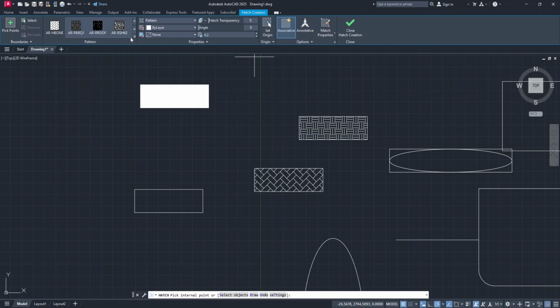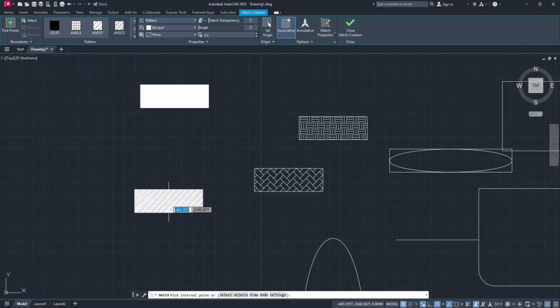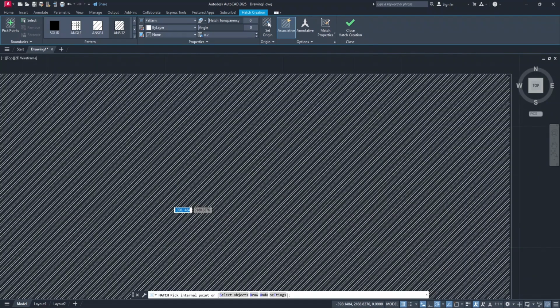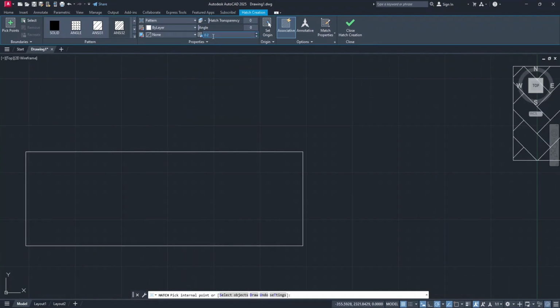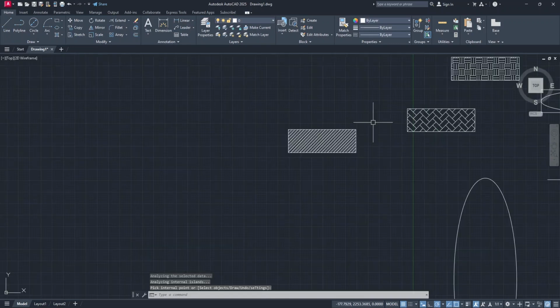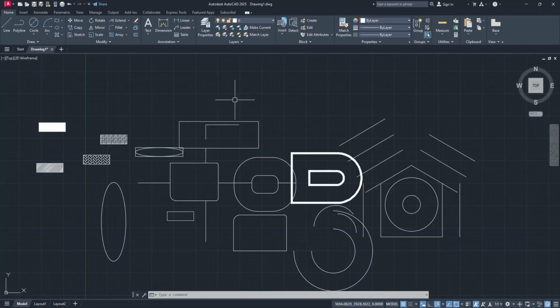Lastly, select parts, look for a different material, maybe something like steel or hard block or something. You can see they are too tiny. So let's try 1, press enter, click inside, and then you get this. Now close it. A shape is a shape until you put a hatch, it then becomes that material. Now a specific tool is given the task to help you organize all of this, which is layers.